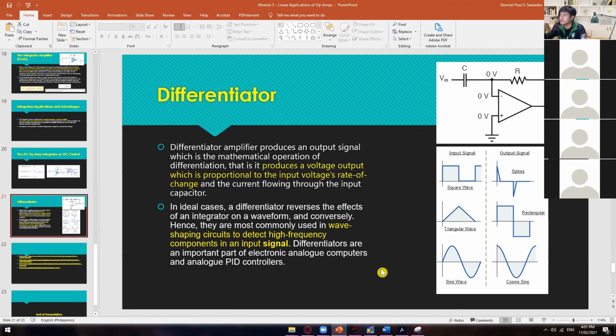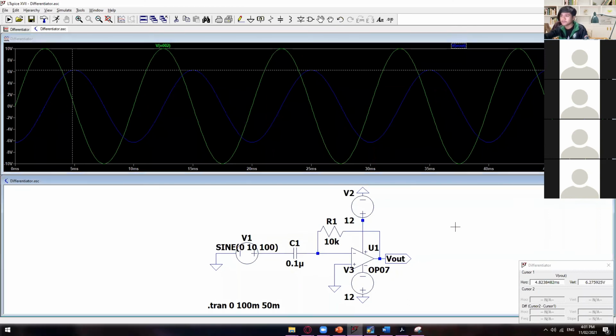So you can find the formula, and then it will only require you the capacitance value, the resistance value, the voltage input, and then the 1/2 pi for the frequency, because frequency is not given. Okay, so let's now go back to the SPICE. So as you can see right here, we have a sine wave of an input and then a cosine wave as your output. All right,